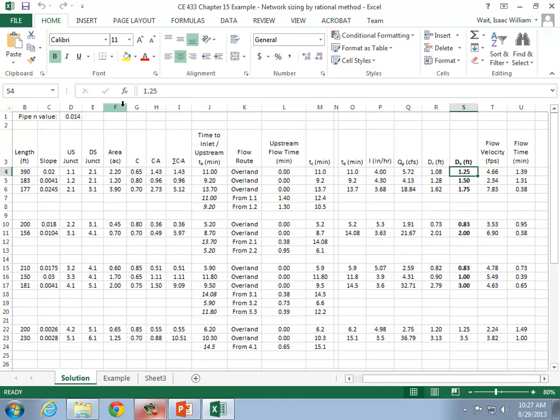And so that ties into your original question of why we are using a different rainfall intensity: it takes a different amount of time for the entire area to be contributing. However long it takes for the whole area to be contributing determines the rainfall intensity that you select for the system.